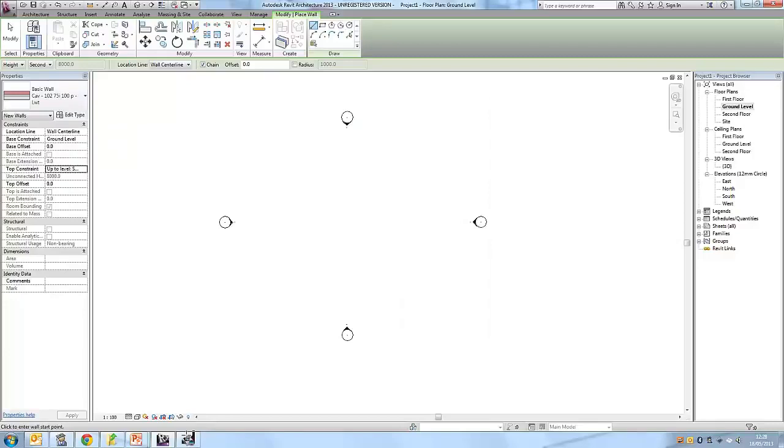now we are going to create our walls. So if I can just drag a wall here, I can make it 15,000 millimeters, or I can just type in 15,000 millimeters. So you can drag to how long you want it, or you can type in by just pressing a number key on your keyboard, and it will bring up the editable box. So I want it 15,000 millimeters, and there you go.